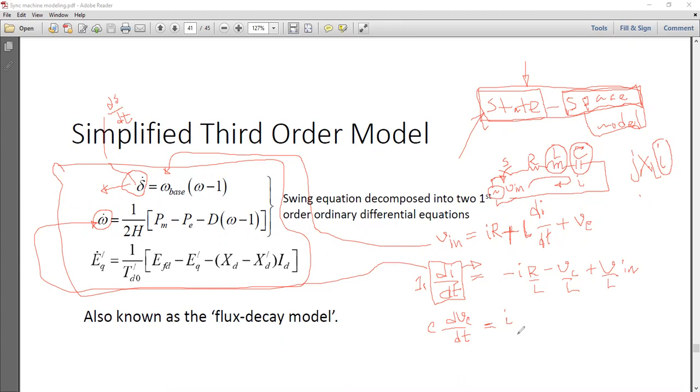Of course, you can take it in the integral form by integrating on both sides. That's your freedom. You have the freedom. But we want this equation or dynamic of this RLC circuit to be identical or similar looking to this one over here. So that's why we are keeping it in the differential form. We want ODEs. We don't want the integral form. So now again, we want this dVC over dt to have only a coefficient of 1. So that's why we simply erase this C from here and we bring it to the other side like this.